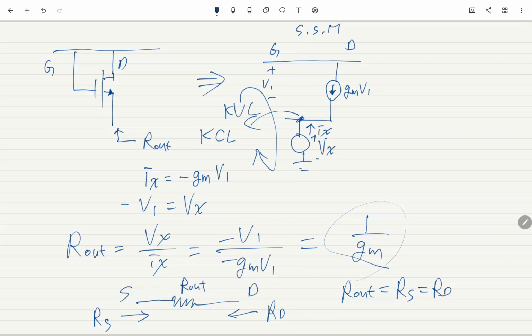If we use a cascode stage, what is the benefit? Yes, high AV. What else? We can eliminate the headroom trade-off. And we also use transistors instead of physical resistors. Why?